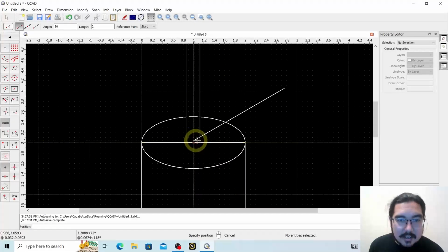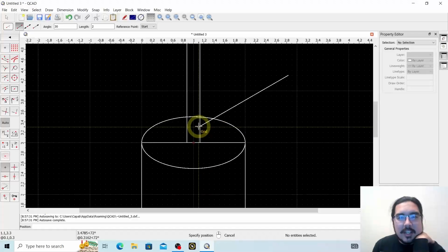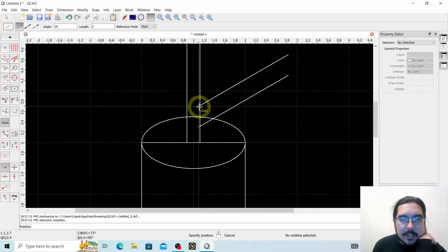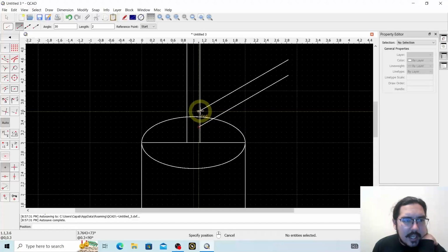I'm going to come down to the middle here. Let's go ahead and place these, let's say, about right here. We want it to sort of stick out over the edge of this. We want the fin to come out this far, one, and we're going to want to place a second one about that far off here. I want the meat of that to be, let's see, this is at 0.33, and we want at least about 1/4 inch. So 0.36 should give us pretty close to where we're going to be, a little above that point there.